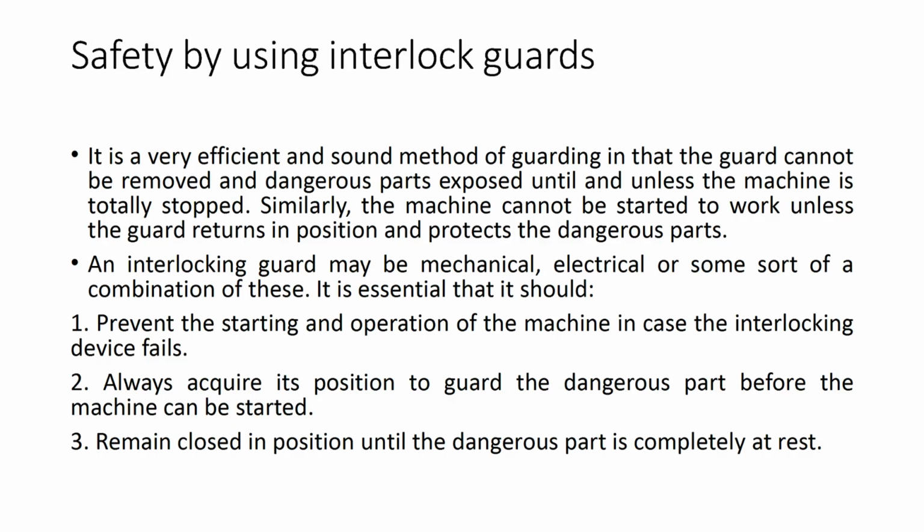It is essential that it should, first, prevent the starting of the machine if the interlocking device fails. Second, always be in position to guard the dangerous part before the machine can start. And third, remain closed until the dangerous part is completely at rest.